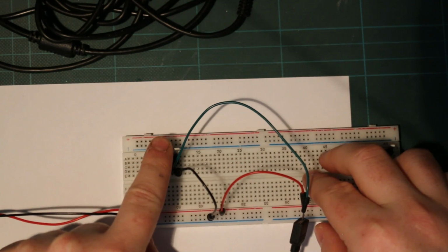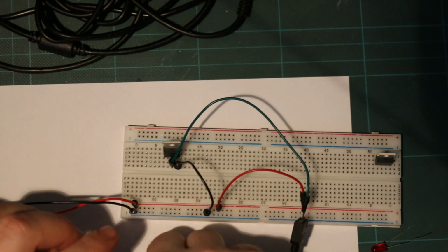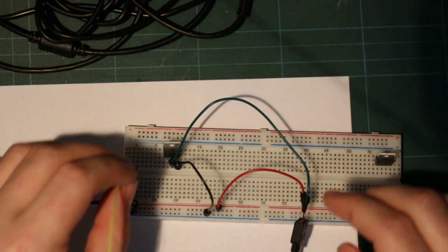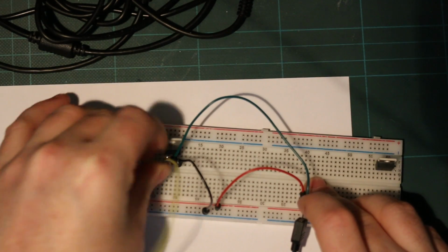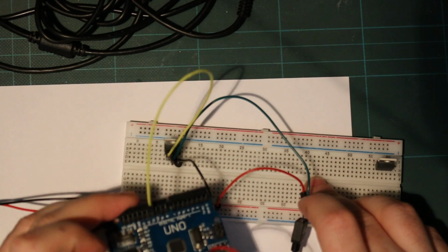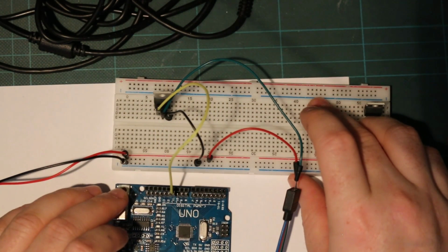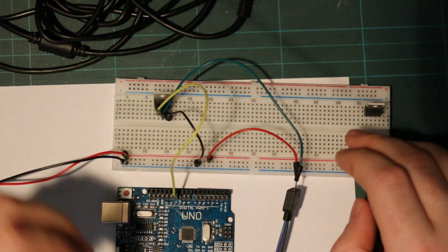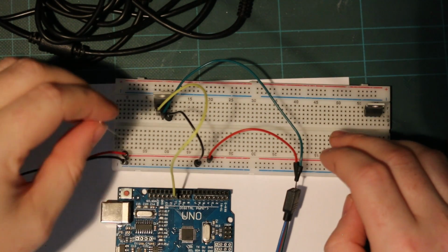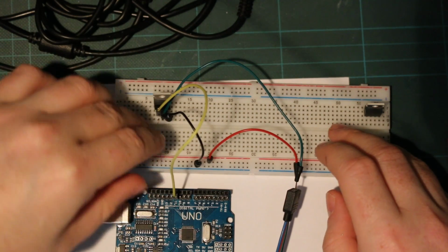Now to actually control when this gets turned on and off, we're going to plug the leftmost pin to the Arduino. As you can see here, see if I can get that all in shot, perfect. So that's now connected there. And as we said before, we need to connect the rightmost pin also with a 10k resistor to ground.